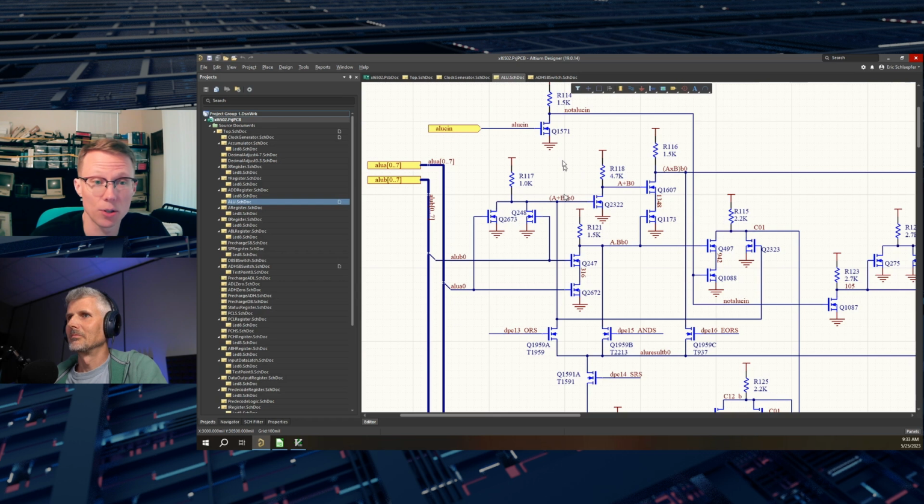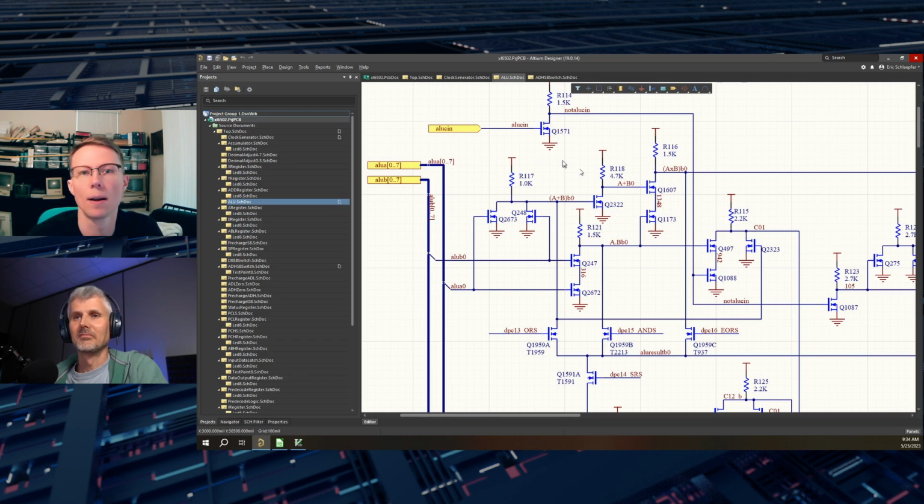I've actually seen the original schematics. Somebody showed me the original blueprints. Nice. The original blueprints were drawn as a way to match the layout. That's kind of how things were done in the 70s. You're designing your chip, you're working with a layout person, and you would draw the transistors and the logic in the order that they would go in on the die to assist with that place and route process.